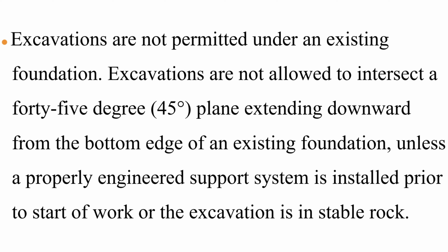Excavations are not permitted under an existing foundation. Excavations are not allowed to intersect a 4 to 5 degree plane extending downward from the bottom edge of an existing foundation, unless a properly engineered support system is installed prior to start of work or the excavation is in stable rock.